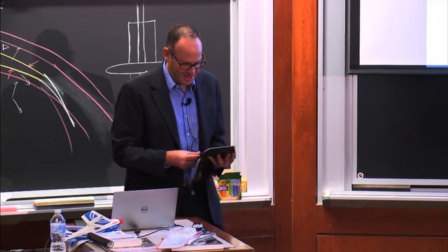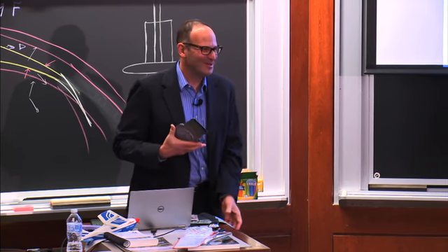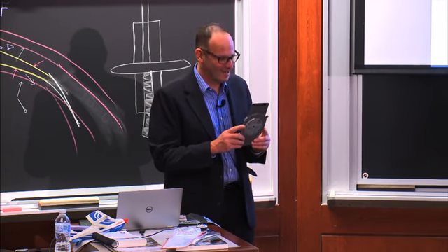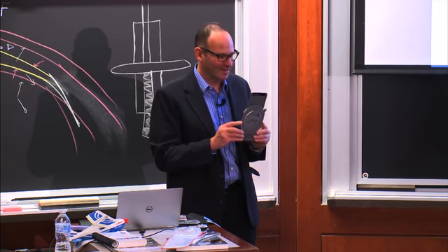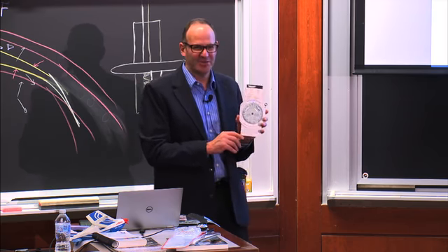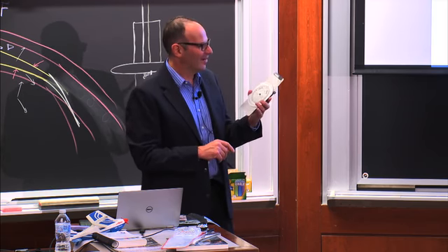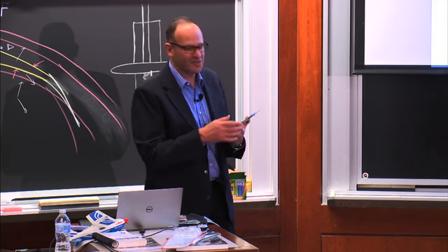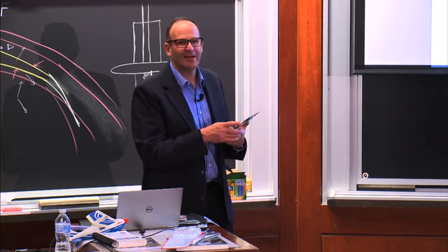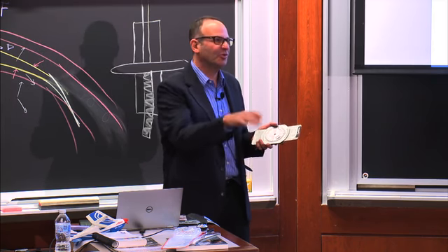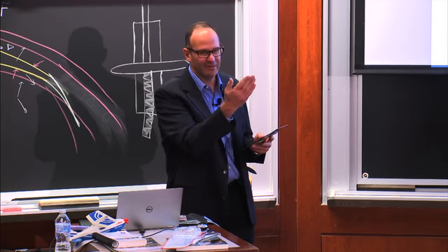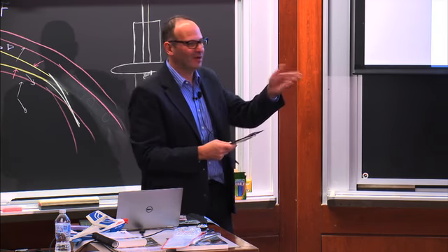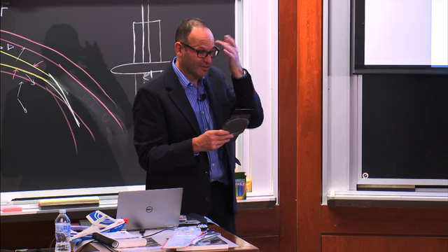This is the E6B flight computer. I think the E6B designation comes from the US military. I'm not exactly sure when this came out. Probably it says in Wikipedia, but I'm assuming it was a World War II era kind of device. And it lets you make all kinds of computations of density altitude, of how fast you're going truly through the air, as a function of your altitude and what you're seeing on your airspeed indicator.